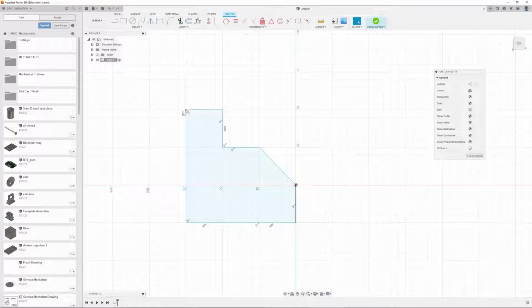And once I completed that shape, it turned a pale transparent blue on the inside. This is the visual indicator in Fusion that this profile is fully enclosed, and you can make three-dimensional geometry from it. We'll get into the three-dimensional tools in just a moment. I plan on doing that as a separate tutorial, where I'll have some more specific objects in mind that we're going to create.